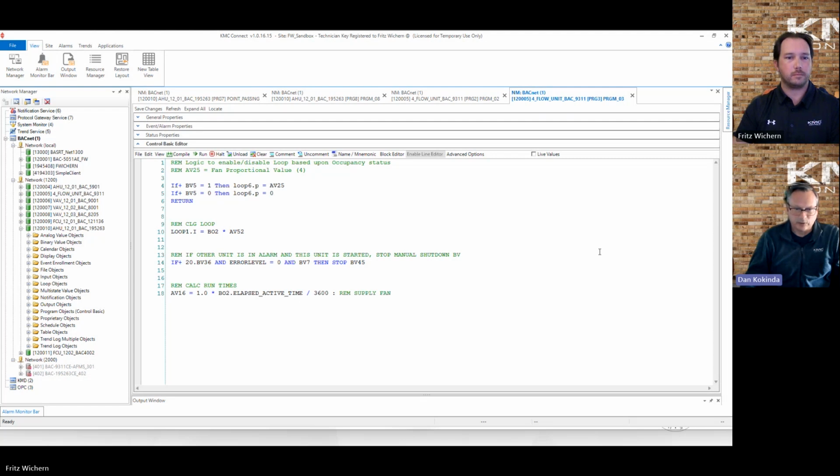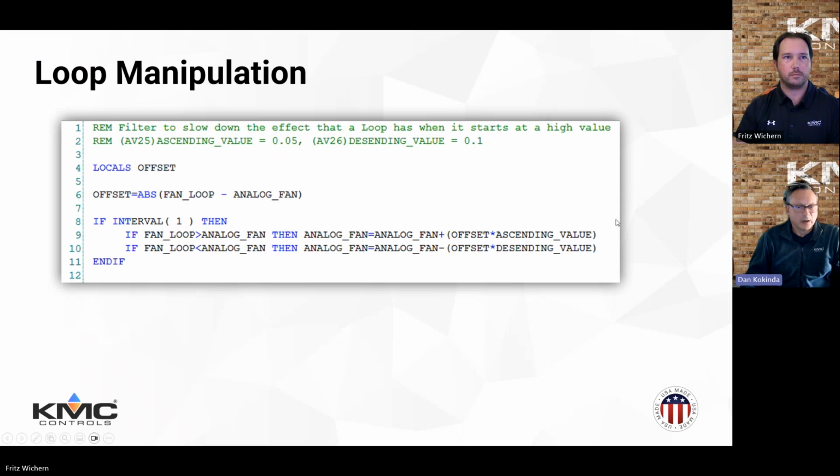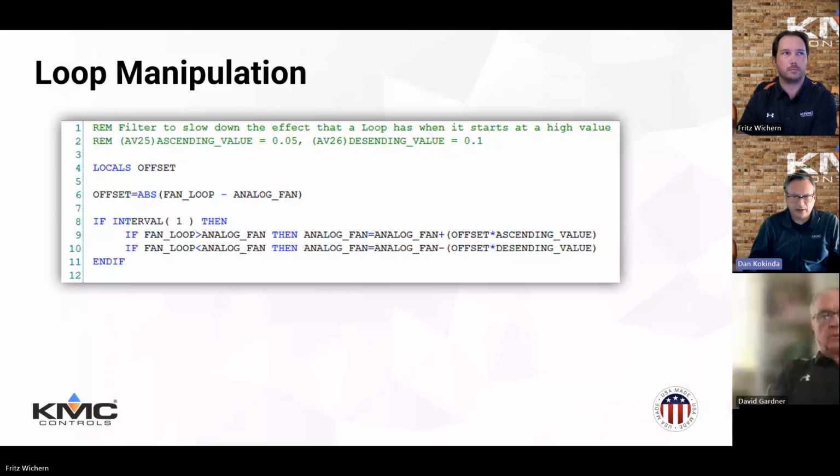So when you do a NetPoint definition, whether you use either none or NAN, I think you can use either one in that instance, if I remember correctly. It's been a while since I've done that. And then somebody had a question about flooding the network, because of course, IP networks are a lot faster than MSTP, and that is true.